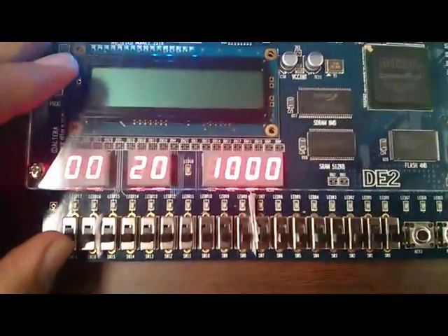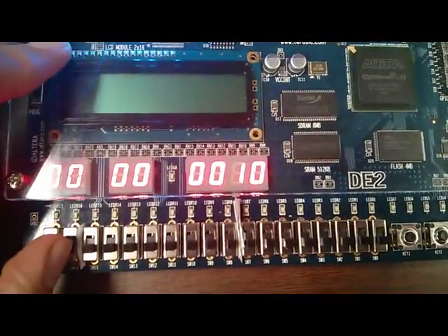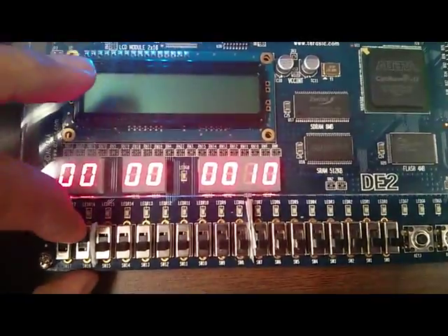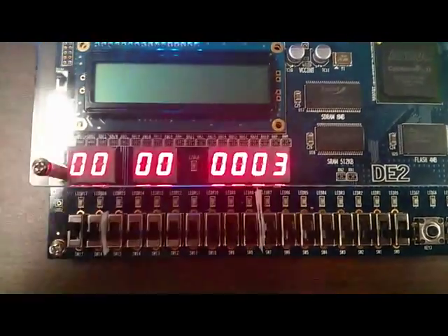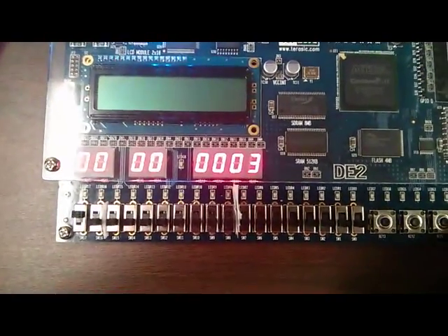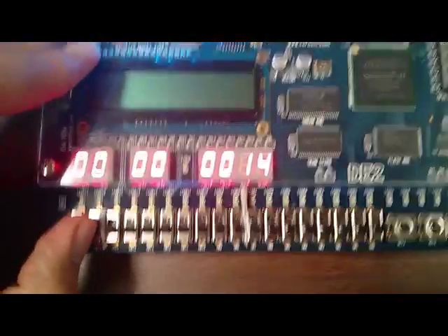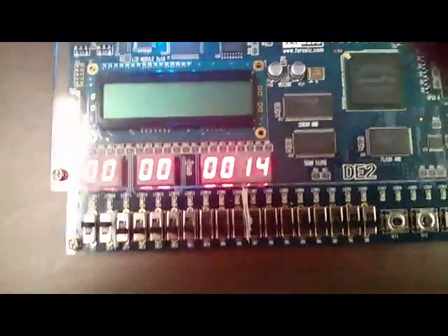That's the correct instruction. Now the output for my ALU should be 5, and my program counter should turn to 14 or 20 in decimal. After I push this button, it's a 5, and that is 14 in hexadecimal and 20 in decimal.